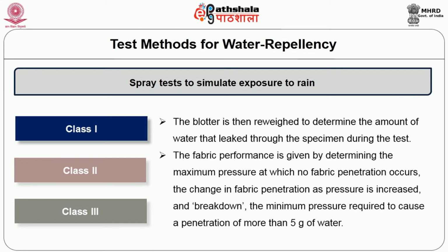The fabric performance is given by determining the maximum pressure at which no fabric penetration occurs, the change in fabric penetration as pressure is increased, and the minimum pressure required to cause a penetration of more than 5 grams of water.